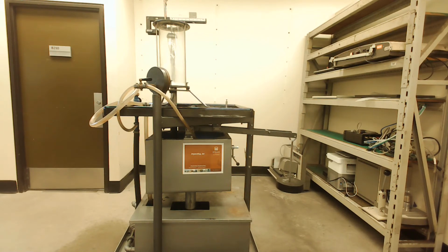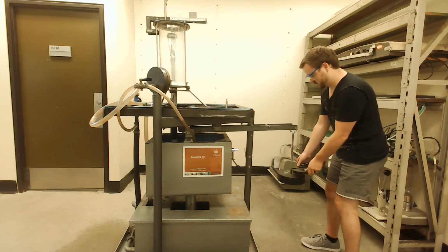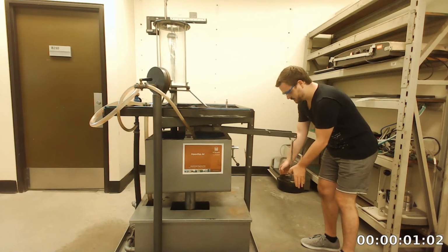At this point, a weight will be placed on the counter end and a timer will be started in order to record the time it takes for the balance to tip over again. Since we know the mass of the displaced water for a given amount of time, we can determine the flow rate of the system.